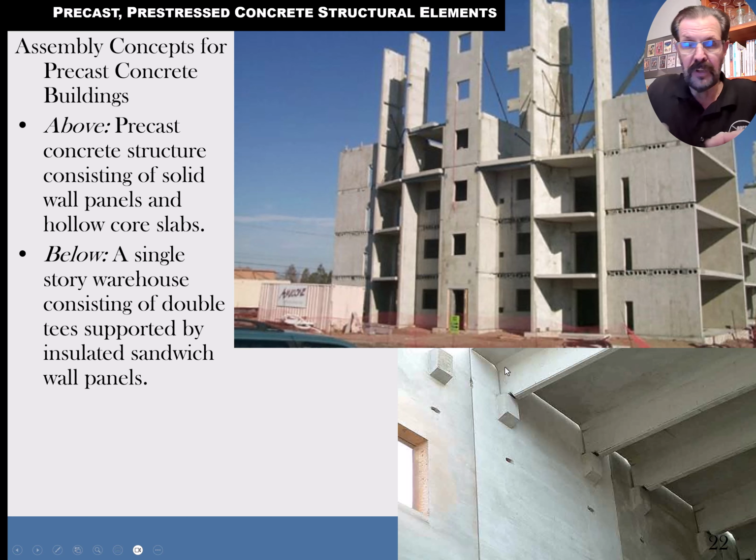And then the two double T's, when they're fitting against each other, lengthways beside each other, there's usually a keyway pocket where the weld plates are joined every so often, maybe every 8-12 feet apart along the length of the beam. Again, the double T. So those double T's get welded to each other also. So a lot of welding goes on with precast parts.